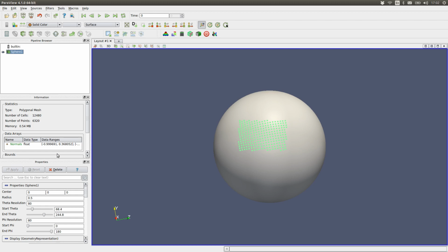We want to be able to look at our CT data. So I can click this object, it's already selected actually, and I can click delete, or I can right click on there and click delete. As long as there's nothing down below in the pipeline, as it were, you can always delete the last object, and we could actually do undo, or keep doing undo from this position, and it would go back, or we could actually click this button and it would reset everything to the very beginning.